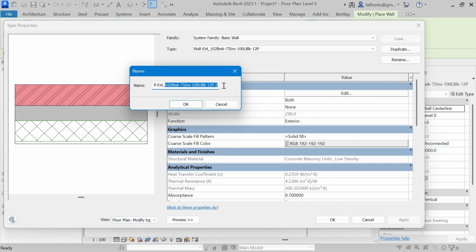You want to have 2mm paint or 2.5, or 2mm paint, and then after that we want to have 10 or 15 plaster, 25 plaster or screed, and then after that 100 brickwork, like that on one side. So the other side we have another one of this.